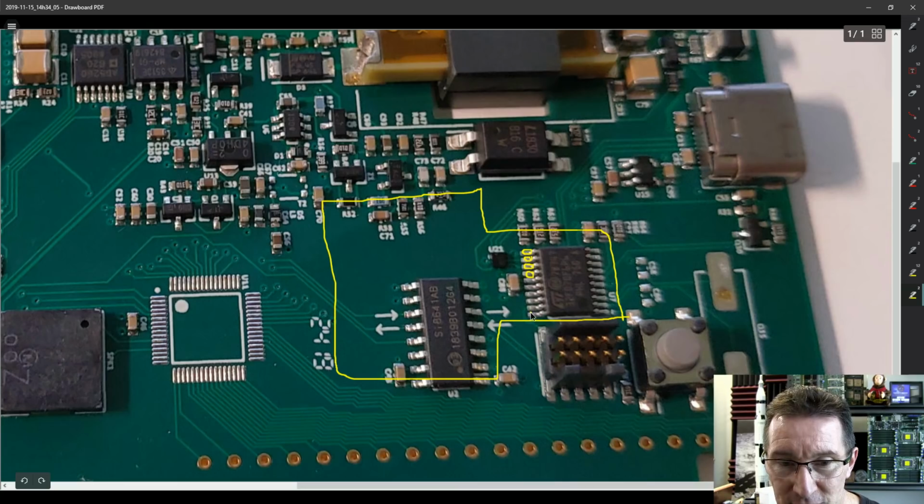And you could actually stagger your vias like this, perhaps. That's a common technique used on LCD ribbons and all sorts of commercial products like that. That just gives you a bit more clearance there to do those pads.